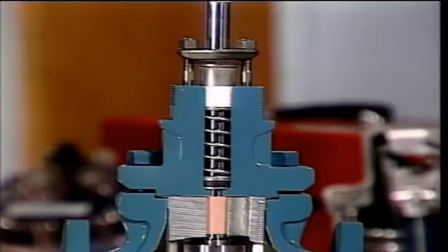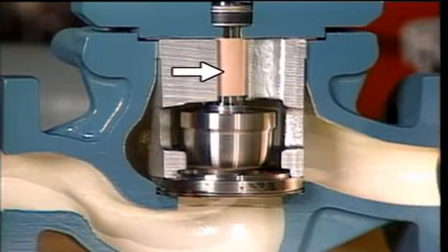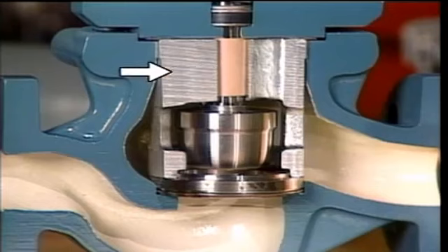For example, control valves, like this one, generally include guides that align the valve stem and disc with the valve seat. These guides help ensure precise control when the valve is opened and closed. The upper stem guide on this valve is housed above the packing inside this part of the packing assembly. This is the lower guide, which is held in place by this part of the valve called a cage. Part of this cage, along with other valve parts, have been cut away to better show the valve's construction.